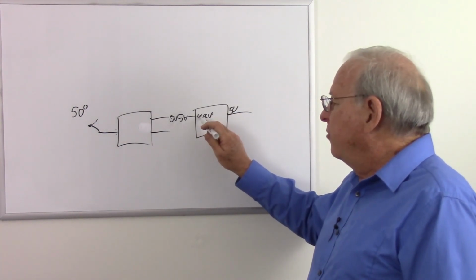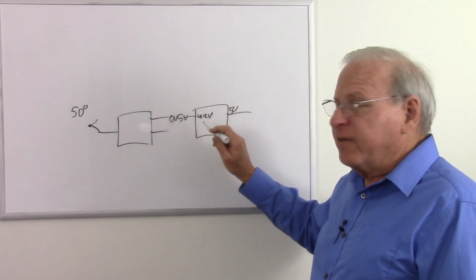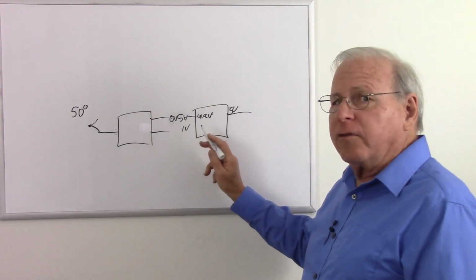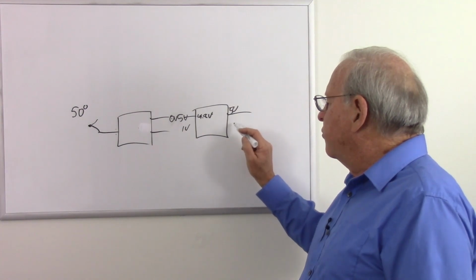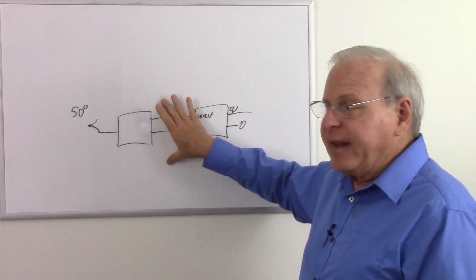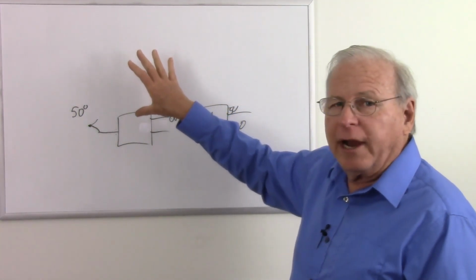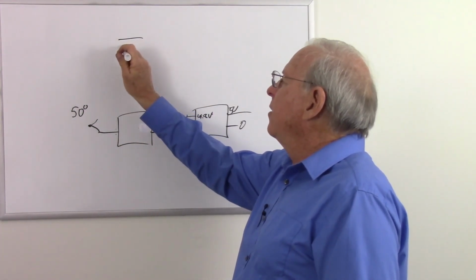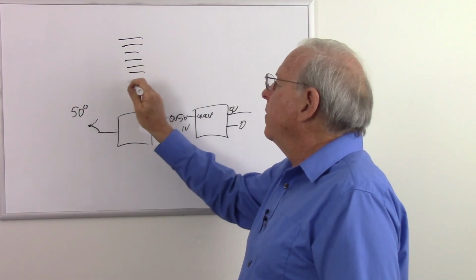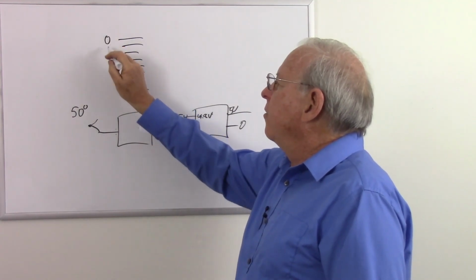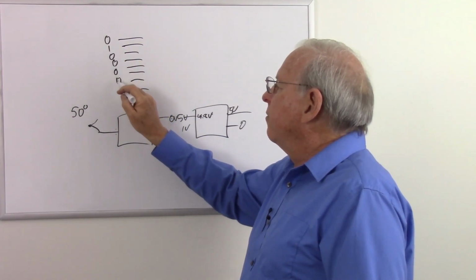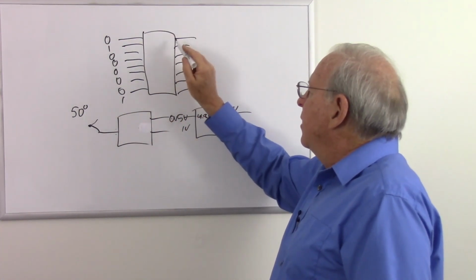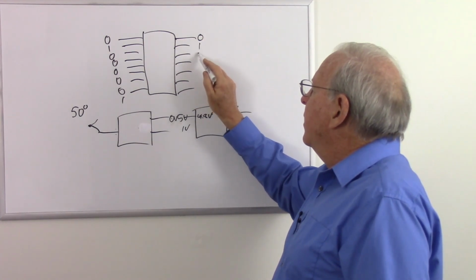If there's a slight change, 4.8 volts is close enough to 5 volts. It says still 5 volts. And if it comes in at 1 volt instead of 0 volts, it says, it looks like 0 volts to me. So the data is going to have high integrity because we introduce small errors. Those errors are cleaned up. So if I have those 8, 16, or how many wires, and I put in 010000001, even though they might get changed slightly, when they come out the other side, it's going to be whatever I put in.